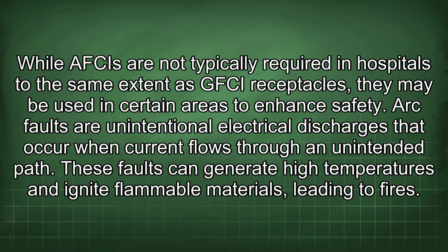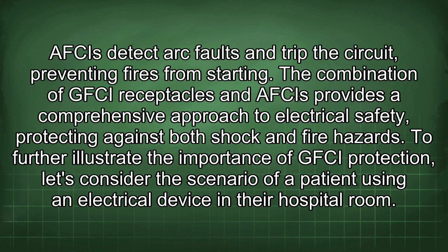Arc faults are unintentional electrical discharges that occur when current flows through an unintended path. These faults can generate high temperatures and ignite flammable materials, leading to fires. AFCIs detect arc faults and trip the circuit, preventing fires from starting. The combination of GFCI receptacles and AFCIs provides a comprehensive approach to electrical safety, protecting against both shock and fire hazards.